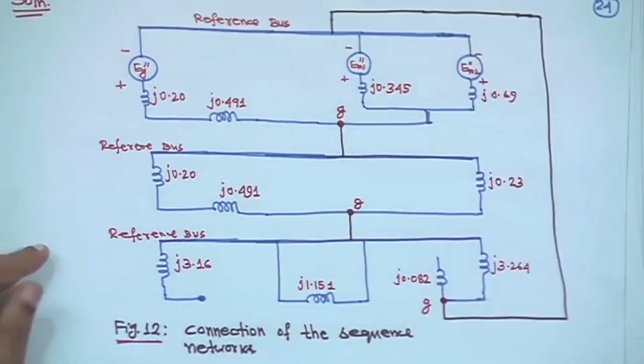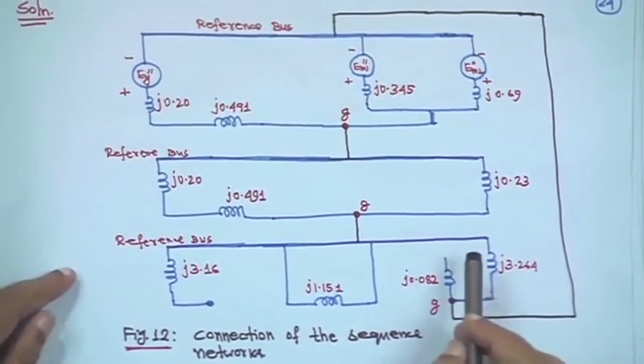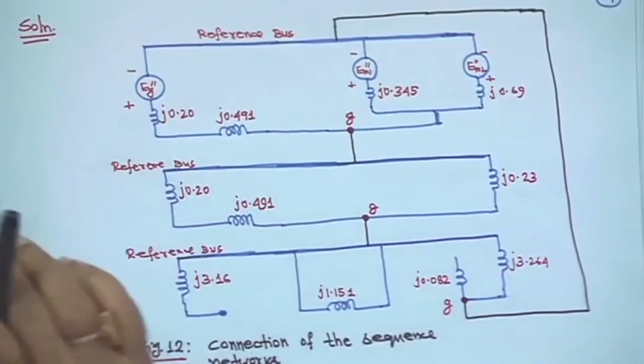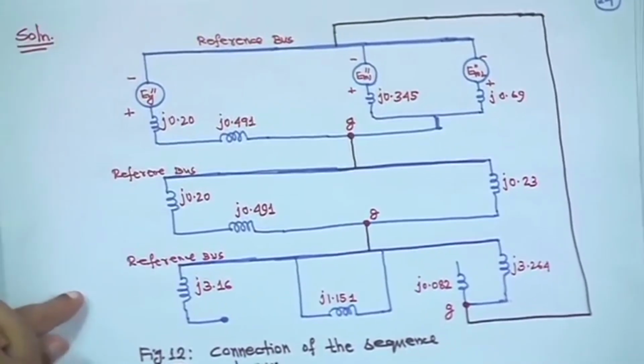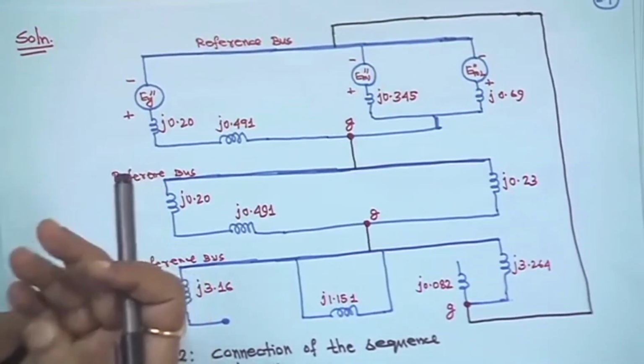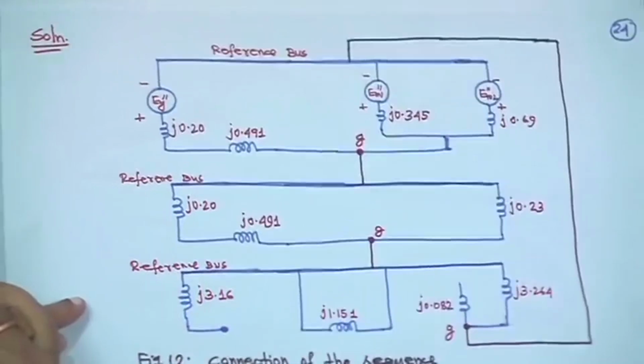Before solving this problem, when you solve it for a 3 phase fault, we took out the pre-fault voltage and used the equivalent Thevenin representation. For the 3 phase fault, our objective was only to see the Z bus building algorithm, which is a little complicated, with a few problems to solve. But here we have given more emphasis to symmetrical components and unbalanced faults.